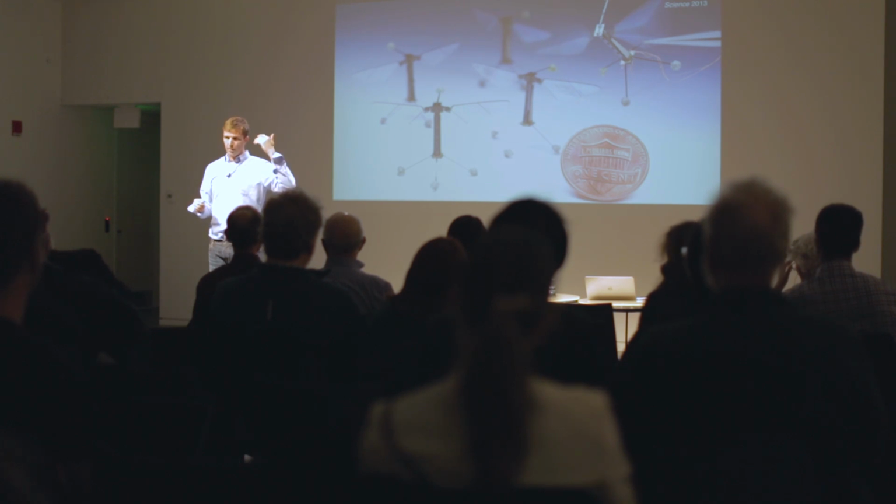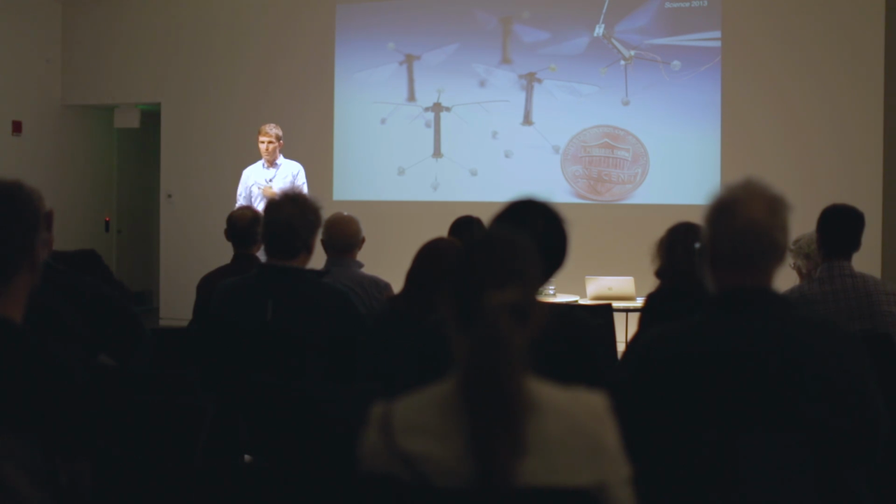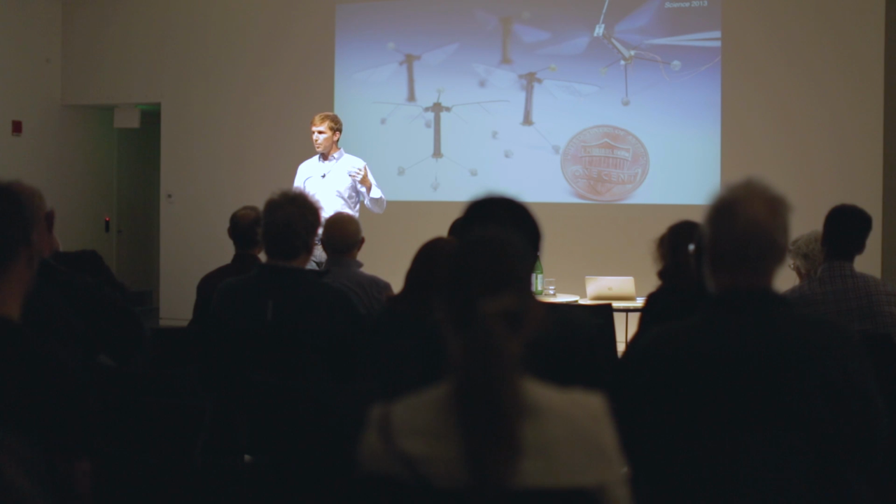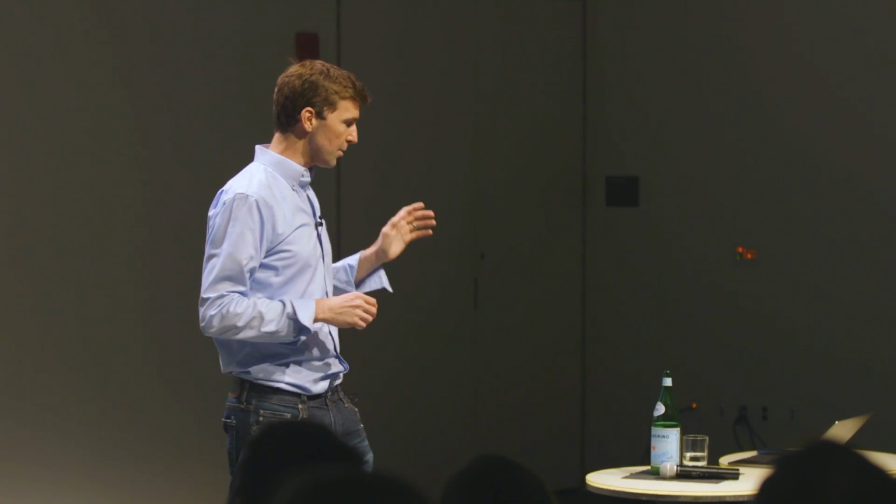And I'm an ignorant roboticist. I just said, okay, well, that means 2 degrees of freedom, 2 actuators per wing. But it turns out that's not a very efficient way to do this, because as you're actuating these devices, and we happen to actuate them at resonance for purposes of efficiency, you have a 2-input, 2-output system that you're operating at one of the resonant modes, and you're going to be throwing away energy into the other resonant mode if you do that.